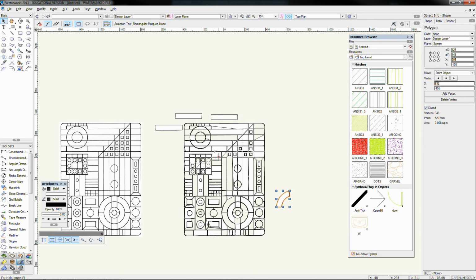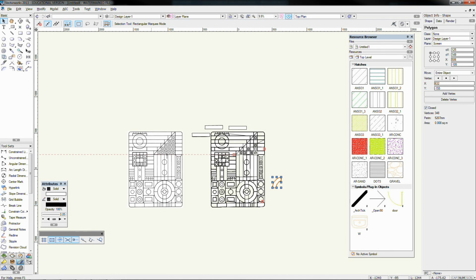Sometimes you might bring an object in. A really simple bitmap normally works very well for this, just a simple one-line drawing. If you've managed to do that, you might have sketched it on your tablet, scanned it in, anything along those lines. Give it a go inside Vectorworks, and maybe you don't have to trace it out like all of us did doing this exercise when we did it back in 2B or whatever it was. So that's another example of how bringing things in as an image file, bringing in another source material, can be really useful for doing quick and easy tasks in Vectorworks.